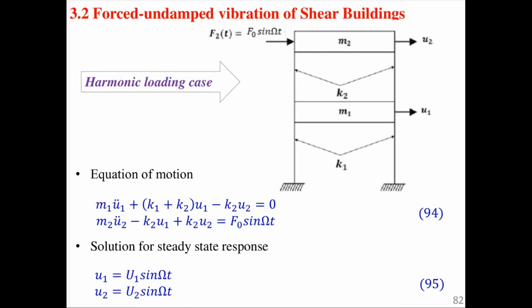But once you understand what is happening, for example, these people would like to see my loading, what is the resultant moment, and the moment that I'm using to do my design, you'll be able to understand the report and sort out the more important aspects from the inconsequential parts. And you'll be able to understand what kind of equations are being solved, and if there is an error or some ambiguous results, you may be able to question that. So that's why we do the manual calculation first. We understand what's happening. Then when we deploy the software, we are not just doing it blindly.